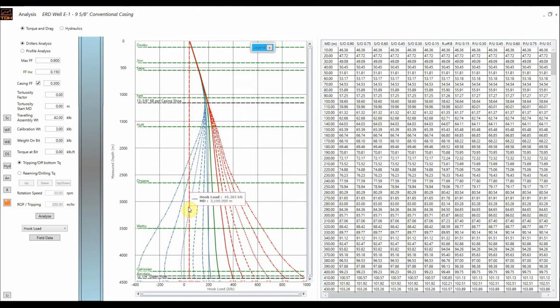We are expecting to see a friction factor of 0.6 from our offset well review, and based on this, we'll be able to run the casing to around 3,100 metres before we start using block weight to move the string. We still have another 1,400 metres of pipe to run past this point, meaning as it stands we won't be able to get the casing string to setting depth conventionally due to drag in the hole.